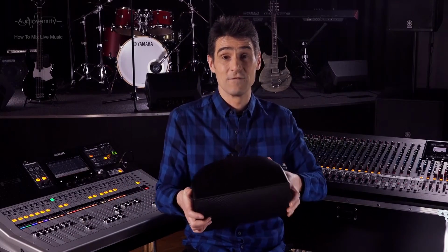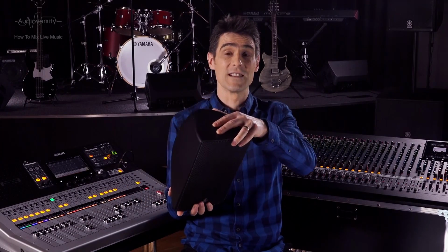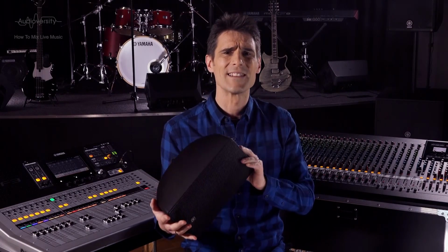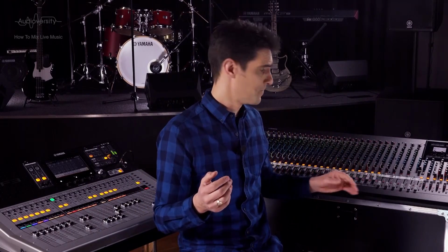For example, the stage might be very wide and the main speakers far apart, so the audience members sitting in the center of the front won't hear so clearly. So you can provide them with front fill speakers and use the matrix to vary the sound mix and the level they hear. Another possibility is for additional small speakers to reach under a balcony, or speakers towards the back of the room to reinforce the sound to the seats at the back. They all may need a slightly different mix and level. So we can use the matrix.